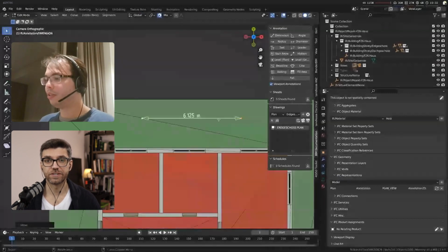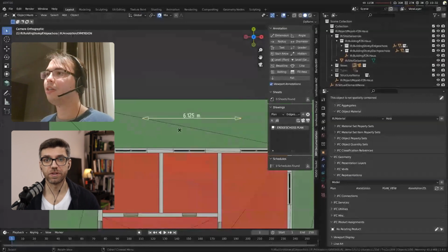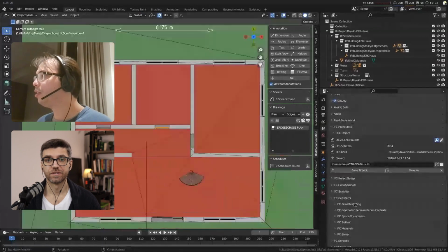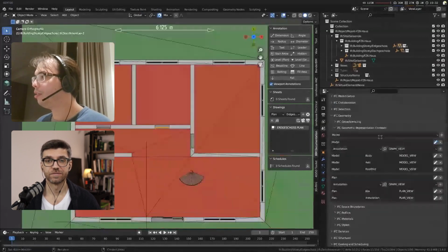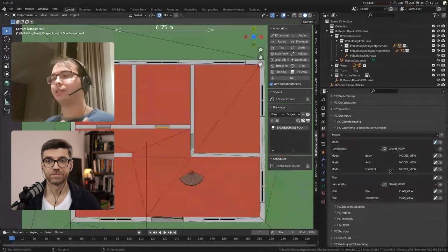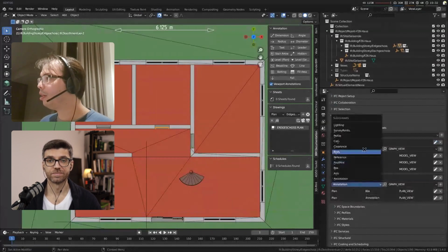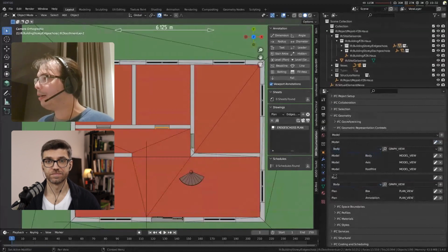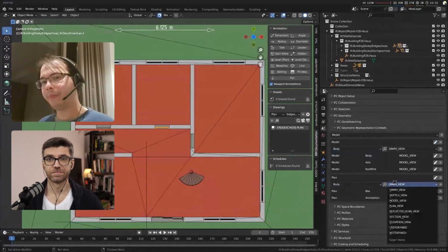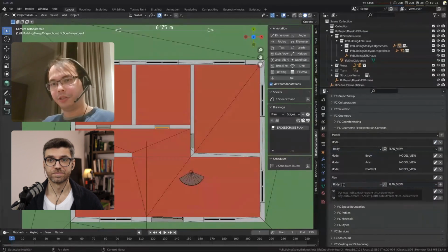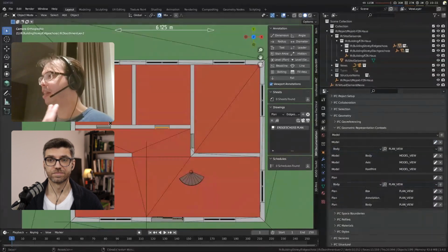So how would you do that? Is it something that you have to do somewhere separately? No, you can do it straight in here. So in fact, let's give it a shot. IFC has a concept, and now we're getting a little bit technical, known as representation context. This is your menu of different types of geometries that you can store in objects. So for example, we might want to store a plan-specific body representation of that window. So we might say in a plan view, we want to have an override. So don't show the 3D cut of it, show it in a particular plan-ish way.